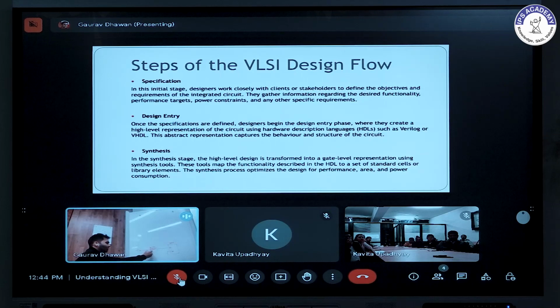If this is going to be at logic 0, your AND gate will always give you a 0, right? Doesn't matter what is the input at this pin. If one pin is 0, your output will always be 0. So the synthesis tool will completely remove this circuit and just put a ground here. This is how a synthesis tool will work, basically to optimize the design circuit and to improve the performance.